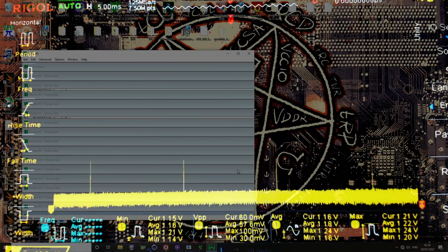And then mode 4 to 5 is, like, 15 millivolts. So basically, I was doing this testing, and I was like, all of these settings are terrible. They're all not really very droopy at all, so there's a bunch of undershoot. The overshoot's fine, but, of course it is. Nobody, we don't care about overshoot here.